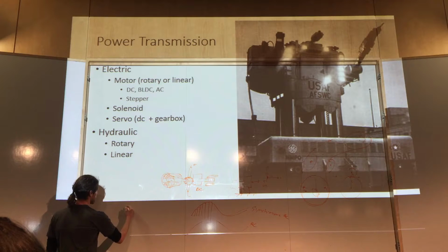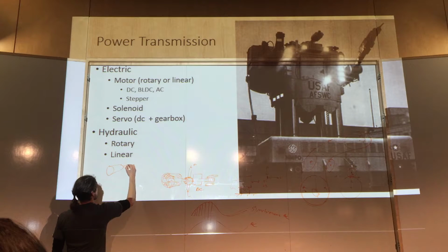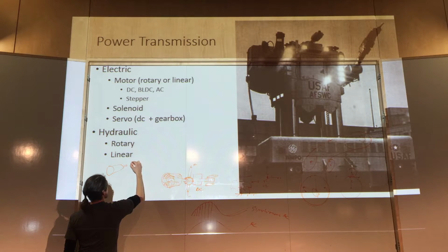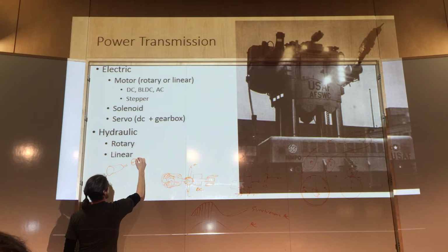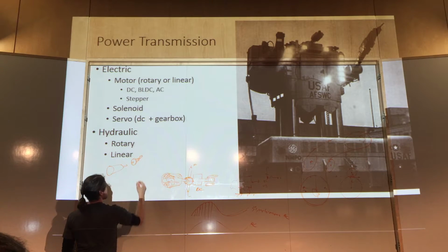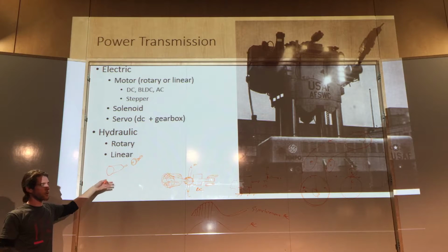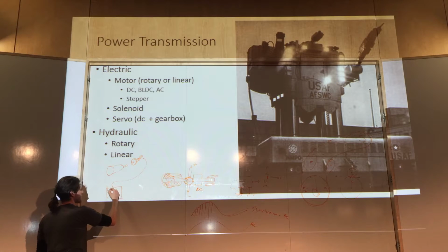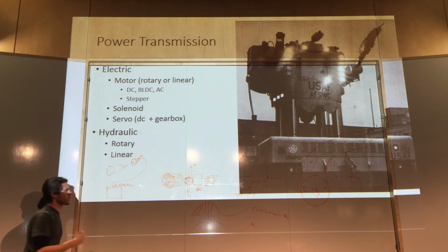So in that kind of situation, you've got your motor, and it's driving whatever. You've got your drive system, and then at some point, maybe at the motor, you're going to have a thing called an encoder attached to it. The encoder usually has like 5 wires coming off of it, and it's literally just counting the rotations for you, counting the angular position. You bring that back into your controller and use that to keep track of your angle and direction. That'll help you close the loop and actually drive the system.